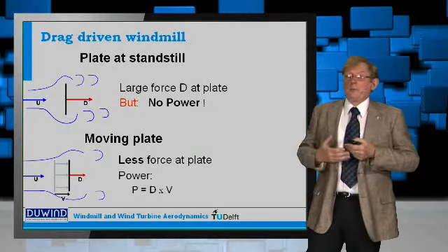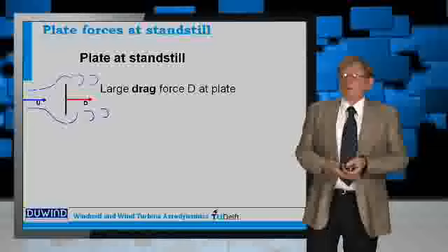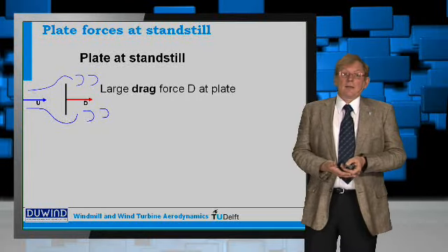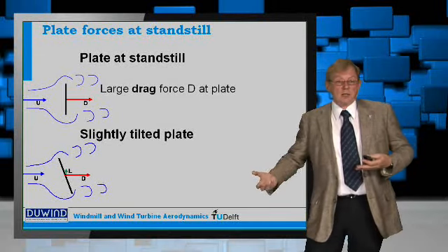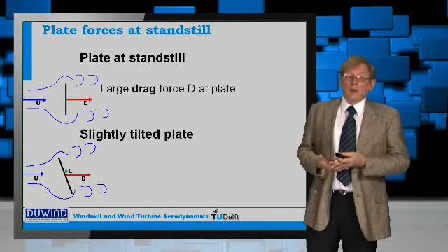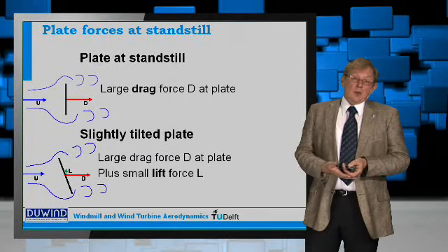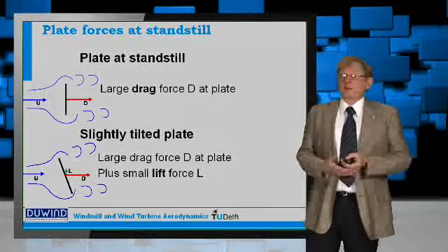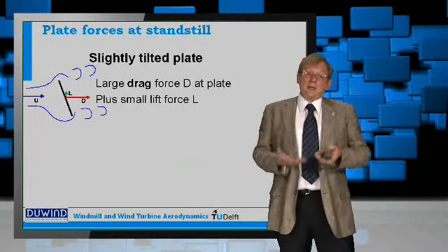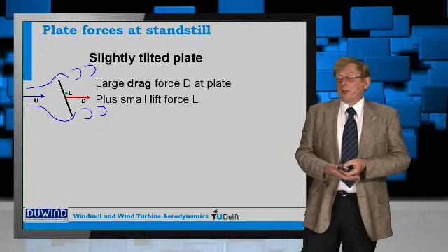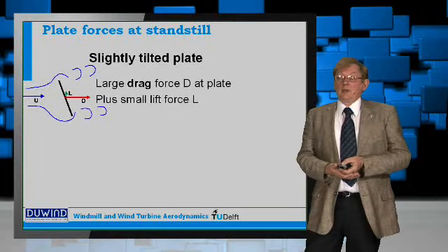But we can get plates working in a different fashion. Let's start again with the plate at standstill, but now we take the same plate and we just tilt it a little bit. Then you will see that apart from a large force in the direction of the wind, you have a small force in a perpendicular direction. That's a force that we call lift. So far, so good. But what can we do with slightly tilted plates? The same picture again: a force in the direction of the wind, which is called drag, and a small force perpendicular to that, which is called lift.